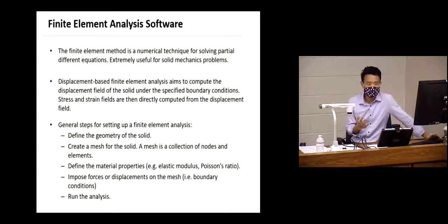So how do we decide that? One way of doing it is to compare your model to a very simple analytical problem with established analytical solutions. Okay? Think about a beam bending problem. You can calculate the displacement very precisely analytically. That does not require numerical methods.